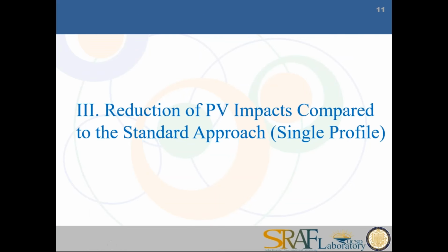So clearly solar power systems do have an important impact on the voltages on the feeder. It's however highly feeder dependent, so as we will see, some feeders, even at very high solar power levels, have almost no impacts.